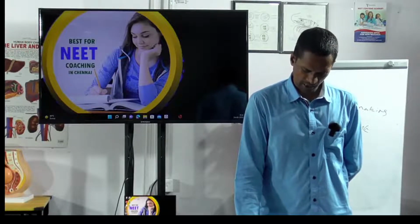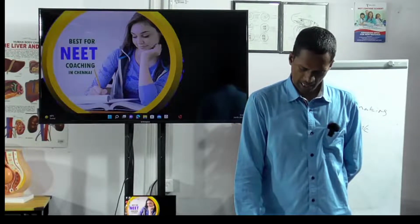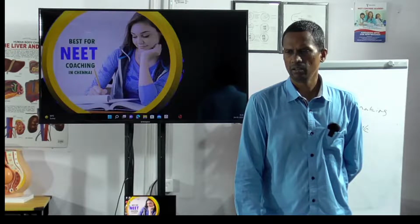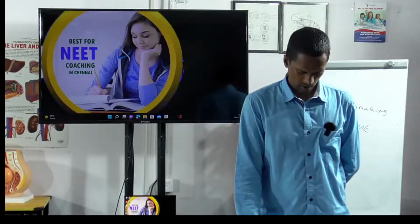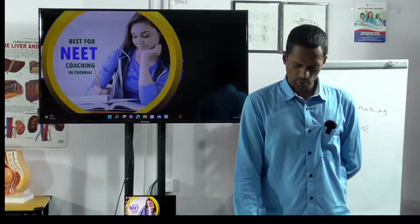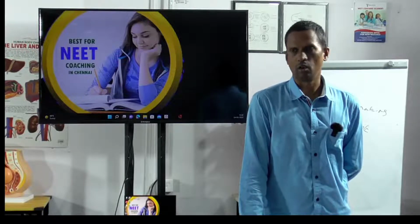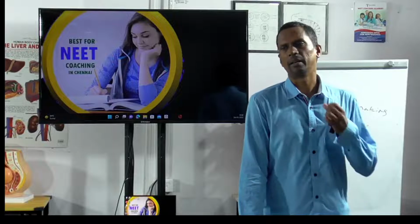For a step down transformer we will have Np greater than Ns. Another relation: Is is equal to Np by Ns into Ip. What is Is? Current of the secondary coil, and Ip is the current of the primary coil.